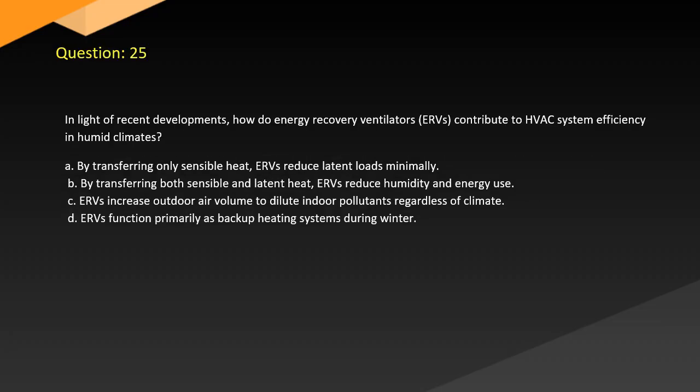Question 25. In light of recent developments, how do energy recovery ventilators (ERVs) contribute to HVAC system efficiency in humid climates? A. By transferring only sensible heat, ERVs reduce latent loads minimally. B. By transferring both sensible and latent heat, ERVs reduce humidity and energy use. C. ERVs increase outdoor air volume to dilute indoor pollutants regardless of climate. D. ERVs function primarily as backup heating systems during winter.